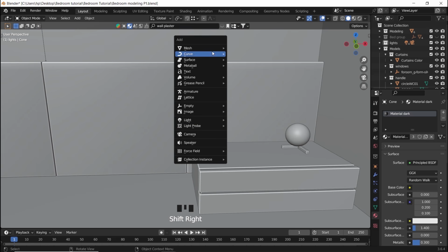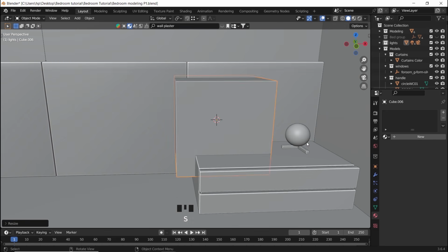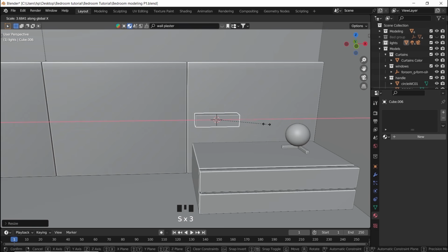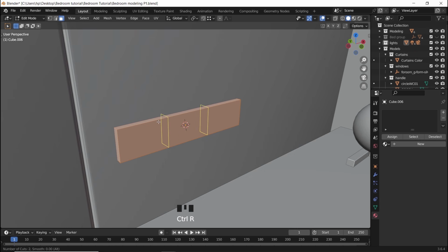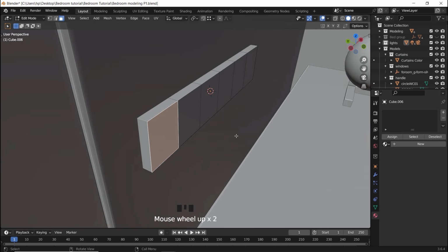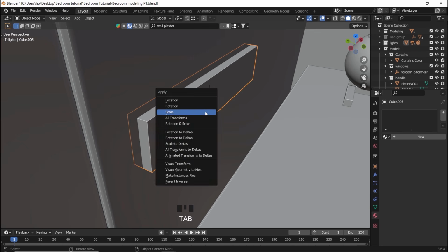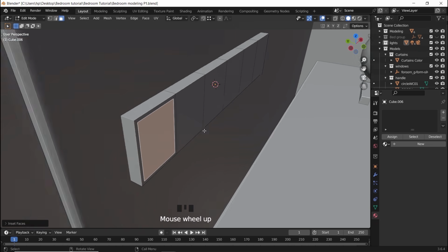Let me also model an electricity socket on the wall. This will be an easy one, just a cube with a couple of cuts. For the socket's opening, use the loop tool to switch the square faces into circles and extrude them inside. Then bevel the shape and give it one of the two materials we have.